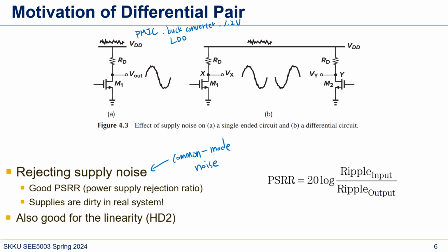There's another reason that the power is noisy. There are lots of other circuits, and even maybe other chips, IC1, maybe IC2. Different circuits and different chips share the same power. That happens. And this chip also consumes a lot of current, right? And this current is not clean.